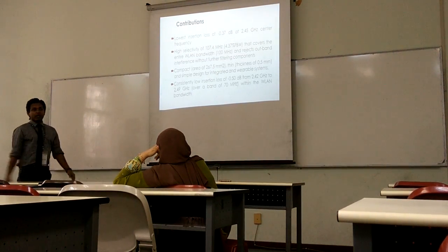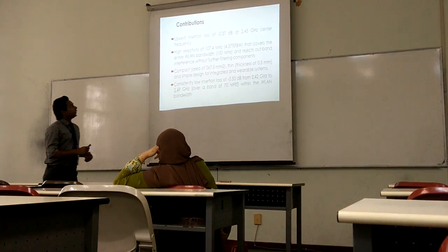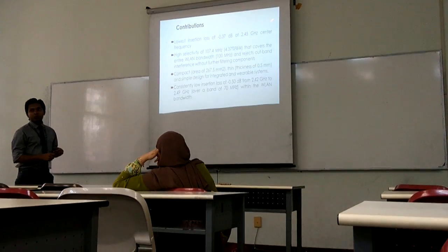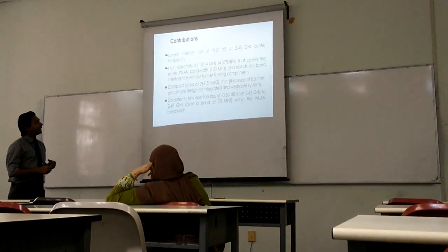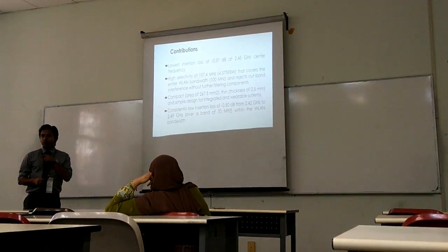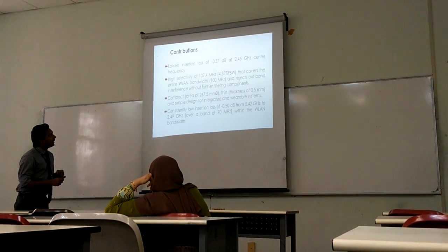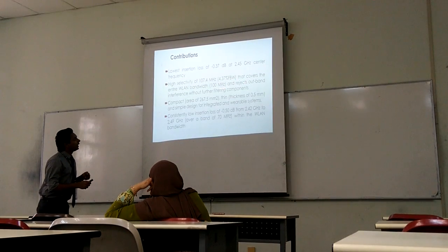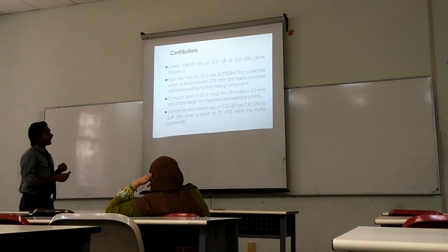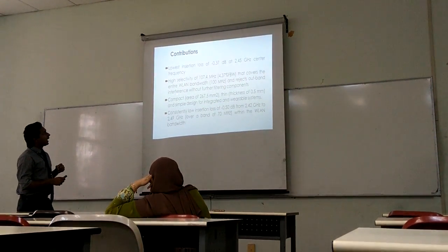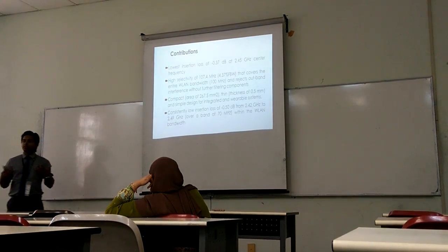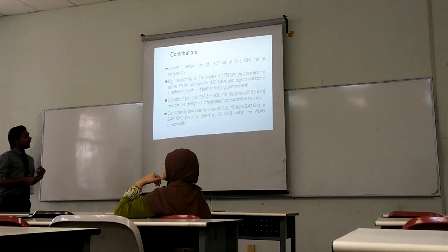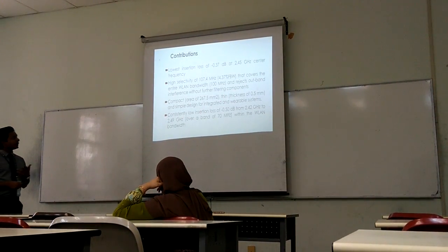So the contributions that we can claim for our work: the lowest insertion loss among recent works we have found, at the center frequency of 2.45 GHz. High selectivity: as I said, the WLAN bandwidth is 100 MHz, and we have selected 107.4 MHz, which is quite close to the exact band of the WLAN, and it rejects the out-of-band interference without further filtering elements. Also, the filter is compact, thin, and good for integrating into wearable systems.